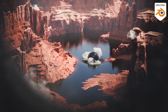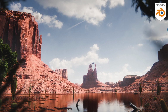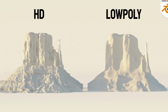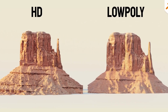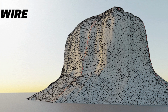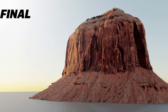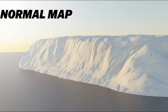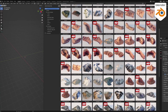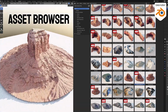And of course, with a lot of details, you're gonna expect a sacrifice when it comes to performance, so this is something to keep in mind. On the other hand, we have low poly models, which offer less quality but run significantly faster than the HD assets. Especially if you have an average machine, you're gonna see the difference. It is also worth mentioning that there is an additional feature for low poly assets, and it is the micro displacement mode, which generates a height map that will help you bring extra details onto your optimized low poly models. And this can be a really handy solution if you have a slower machine, or if you're looking to bring extra details to low poly optimized models.